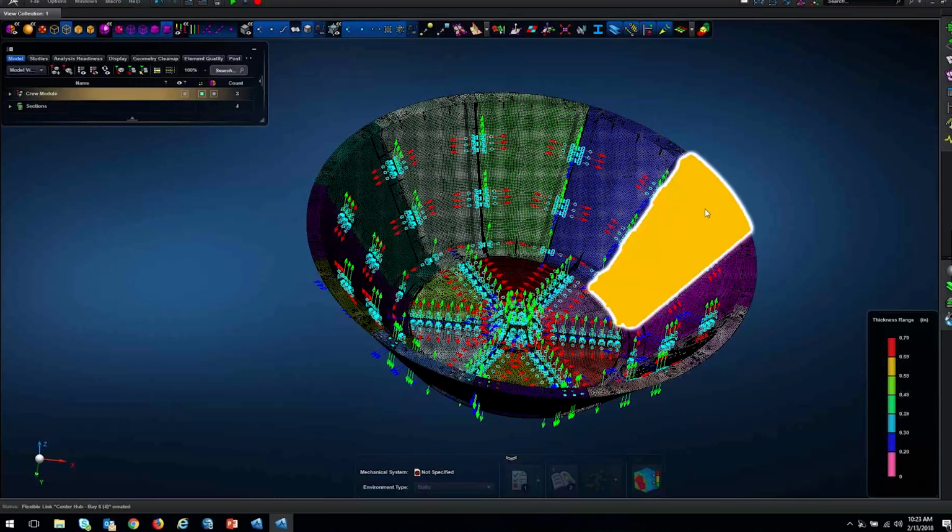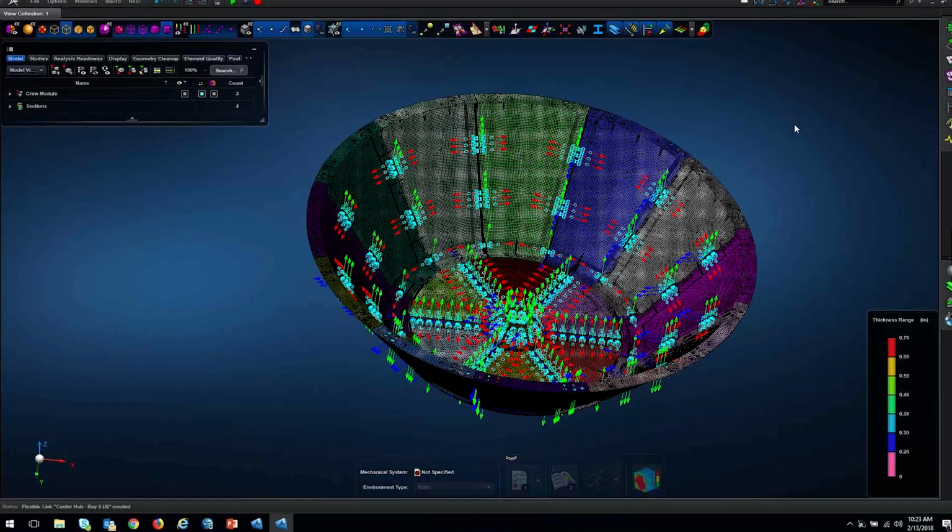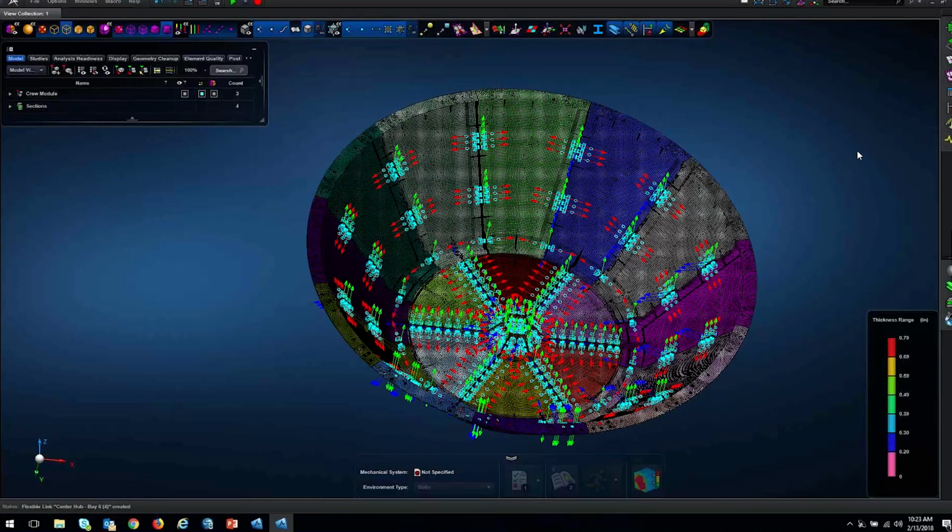And we created the flexible bolts in this case, and the bolt properties are automatically extracted based on the hole diameter. Now let's say you did a baseline analysis, and you could potentially use your edge and vertex drag to modify the hole diameter, and thereby with the generative behavior, the mesh gets updated, and simultaneously because of the hole diameter, the property of the bolt gets updated, and then the new model is just about ready to run the simulation. So now basically with these three scripts, this model is meshed and assembled.